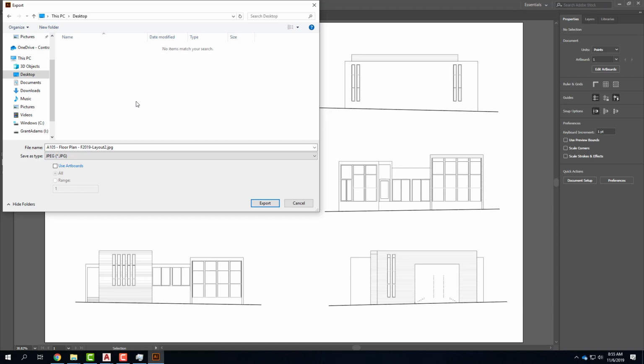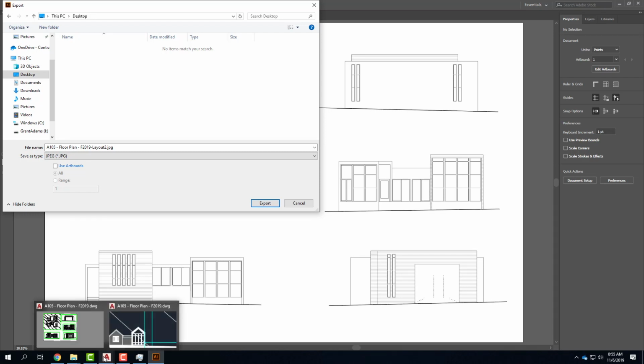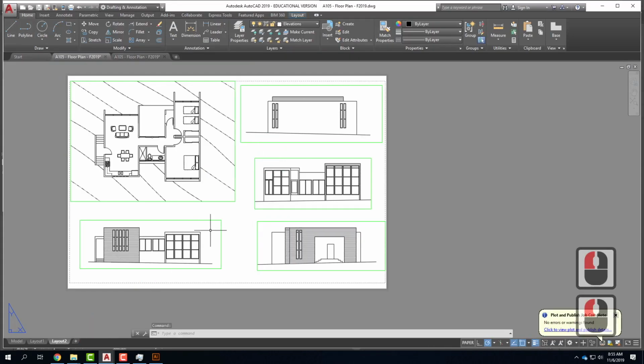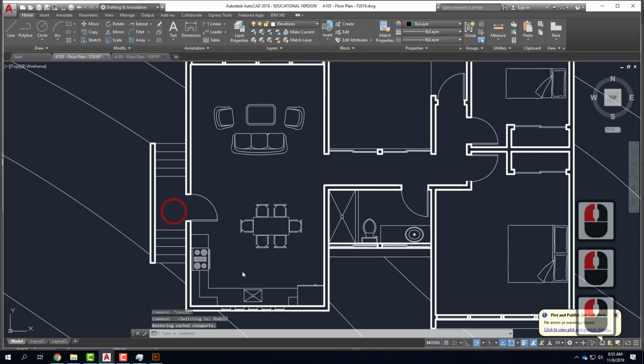Okay? All right, so you guys have about 2 more hours to work. So if you haven't finished your elevations, work on your elevations. Remember, because we're dealing with viewports, once you have your layout set up in AutoCAD, you can go back in Modelspace and keep making changes. And it's always going to be reflected in your viewport when you go to print at the end. All right? You kind of need the elevations set up to do the viewport, though. So work on your elevations first.